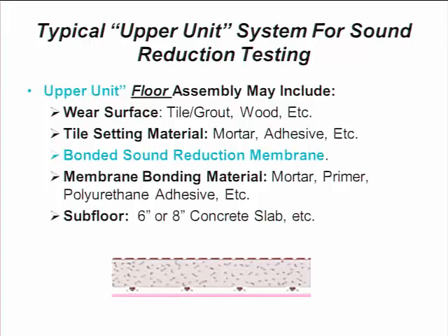In Florida, where I live, everything is a 6-inch slab. Other markets like Chicago, it's 8-inch slab. So it varies depending upon the market that you are in. But make sure that you're looking at a test report that's aligned with the assembly that you're specifying or building or working a project on, because it's important that you dig a little deeper than just looking at a number that says 72.